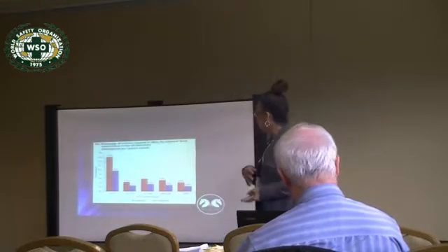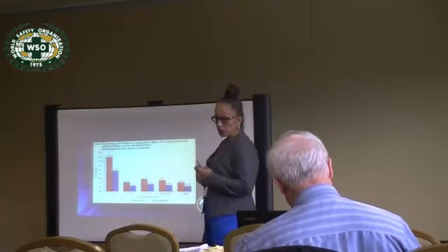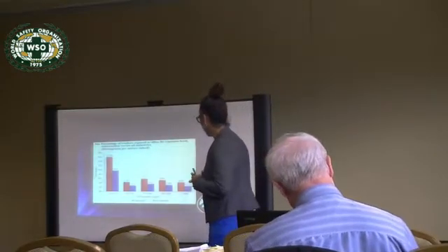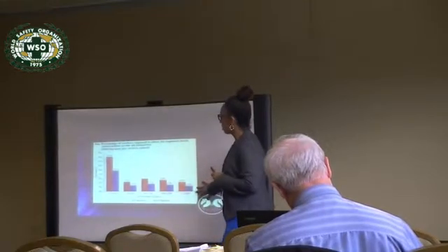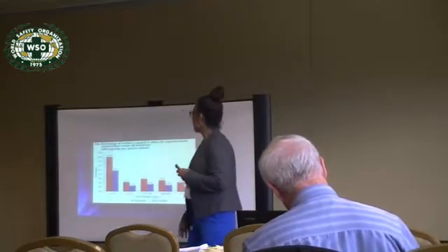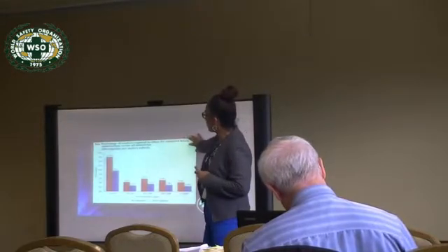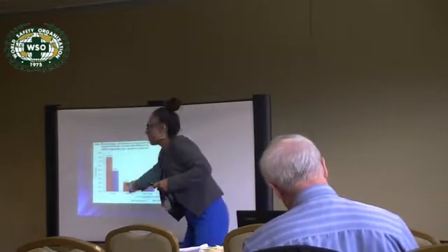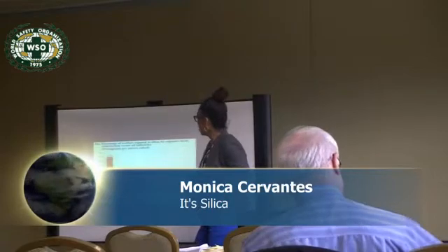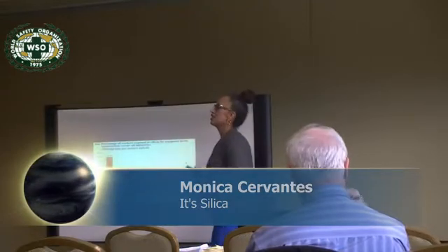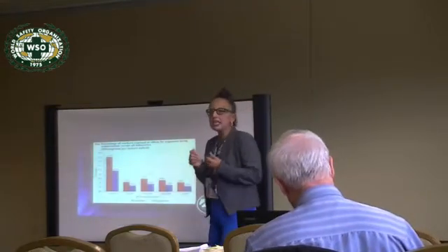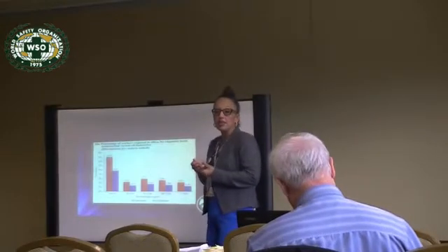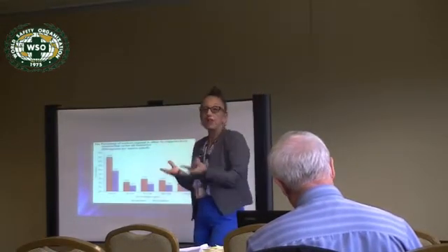Just an idea of construction, because they do deal a lot with construction, and the possible exposure of silica for a construction worker. This is dealing with micrograms per cubic meter: the percentage of workers exposed to silica by exposure level, construction versus all industry. Construction, in the red, is the one where you see more exposure because of countertops, kitchens, drilling, grinding. Anytime you take quartz and you drill and grind, it becomes respirable, as mentioned with the paver. That's why I give the example of the paver, because that's quite common to do.